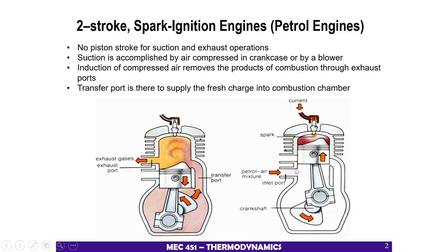The fresh mixture goes to the bottom here, while your piston is being compressed in the induction. The compressed mixture is sparked by the spark plug and combusts. Therefore the piston moves down and the exhaust port is opened to the exhaust.